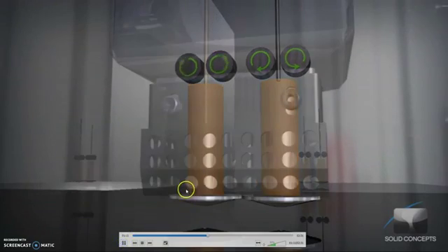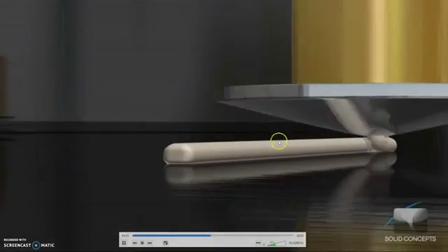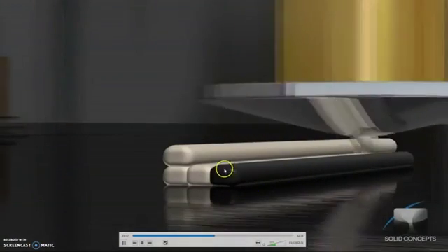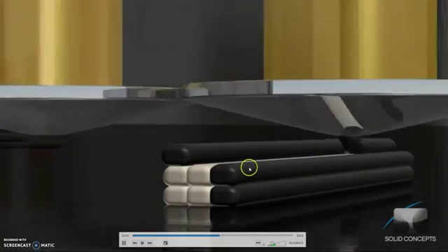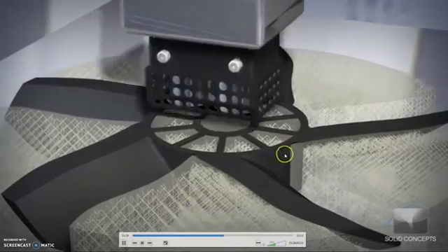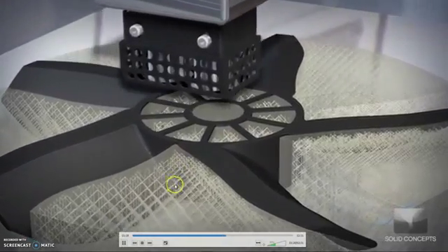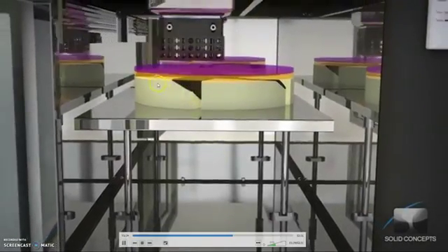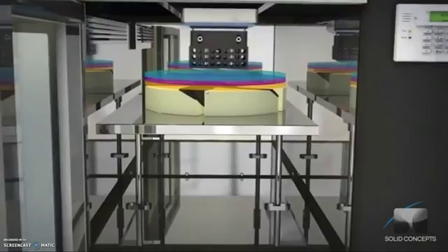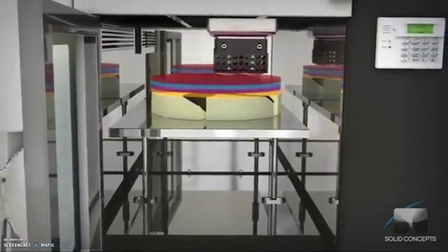So it will feed the support material for one layer, this is the second layer, this is the support and build material, support material, again a build material. So one by one, layer is supporting: support, again a build, support, again a build. Layer by layer we can easily manufacture it. White is the support material and black is the build material. This is 1, 2, 3, 4, 5, up to many resolutions we can go with the layers.